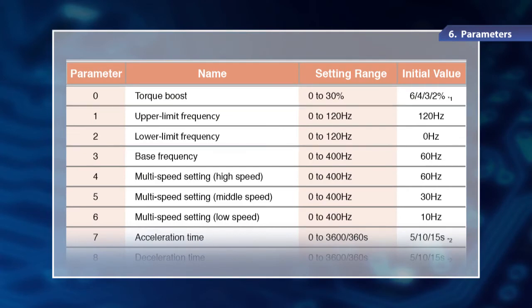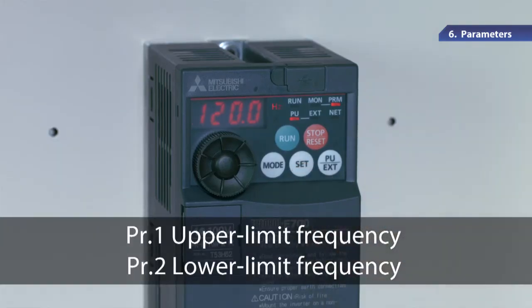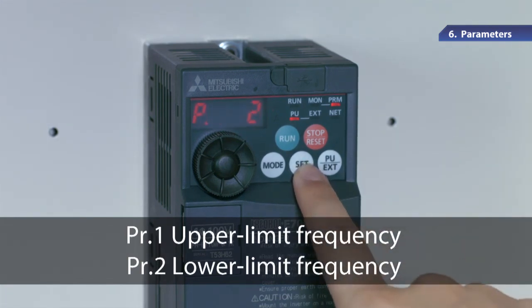Lastly, we are going to set the motor rotational speed. Limit the motor rotational speed so the frequency will be lower than the upper limit and higher than the lower limit. Use parameter 1 to set the upper limit frequency. Use parameter 2 to set the lower limit frequency.